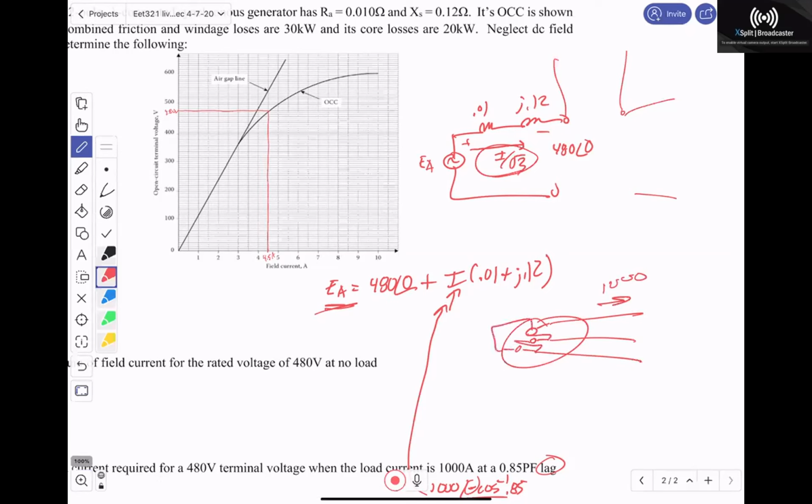Sorry for the ugly figure. That current here is going to divide amongst the 2 units because I've got two connections going to each line. If I draw it this way, maybe you can see it better. I have some current going here and some current going in here. So that's why I have to divide that by square root of 3. So yes.